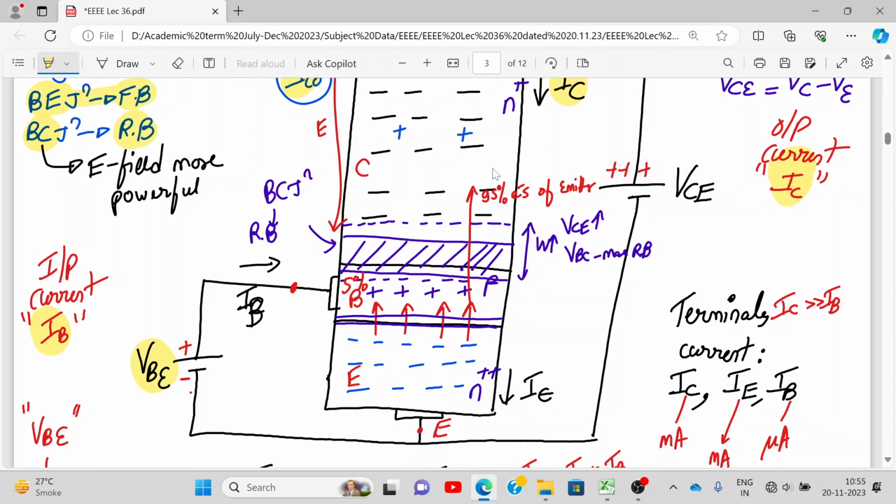So first, we increase the value of VB. What will happen if we increase the value of VB? Conduction starts happening in the PN junction in the base and emitter region. Since the emitter region is very heavily doped, most of the electrons cross the base region. Some of the electrons recombine with the holes in the base region. Most of them are eligible to flow into the collector region. Since the collector terminal is at positive supply, the base collector junction is reverse biased. Most of these emitter electrons flow into the collector. They join the electrons in the collector and hence contribute to conduction of current.